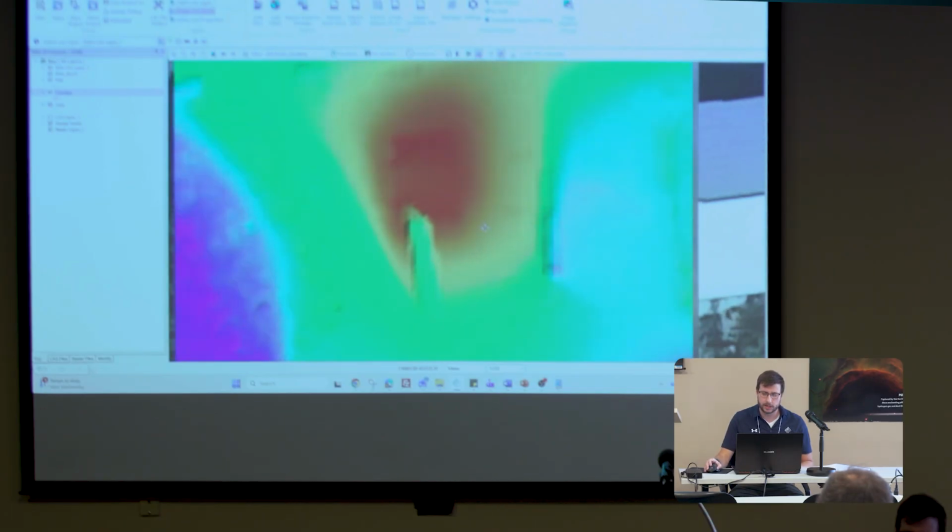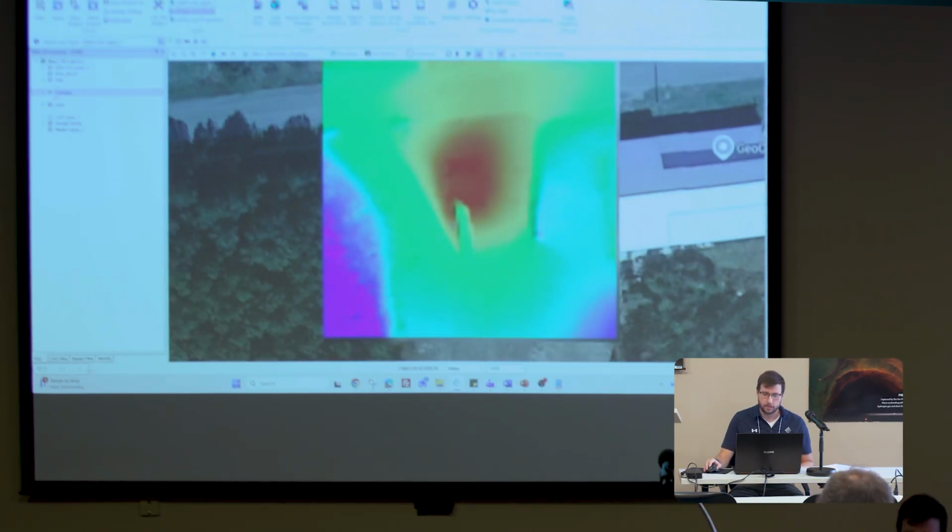So one of the other things that is common when people are working in different CAD packages is that you're very limited in what rasters you can load, and the size and the formatting and things like that. If anybody's using Agisoft Metashape or Pix4D, typically when you make that big ortho, it's got to make it in the Big TIFF format so it can handle the larger file sizes of the orthos.